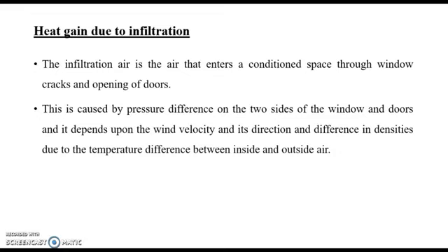The next one is the heat gain due to infiltration. Infiltration is the air that enters a confined conditioned space through the window cracks and the openings of the doors.